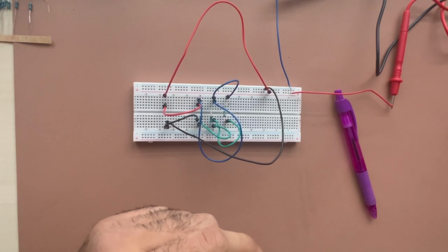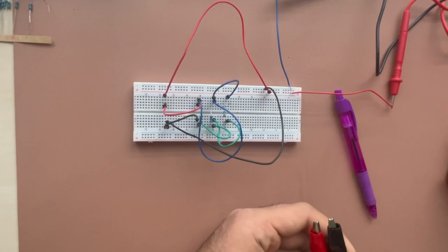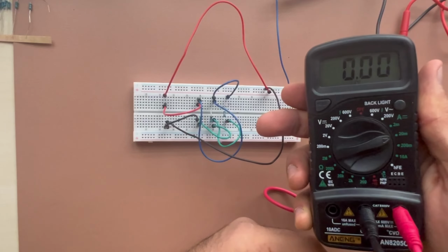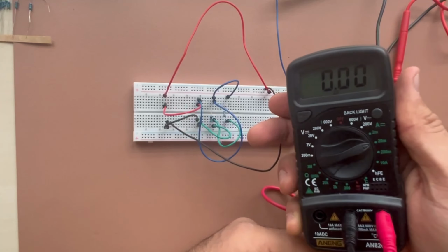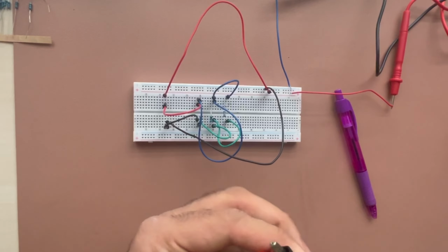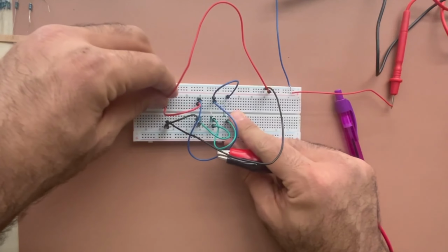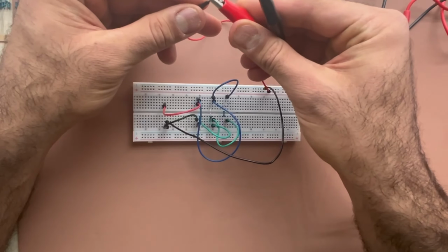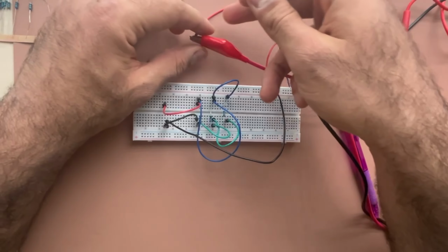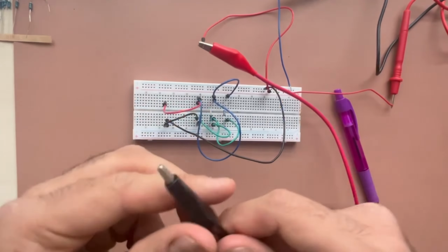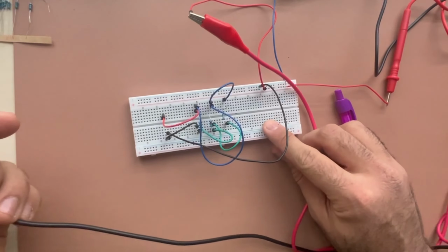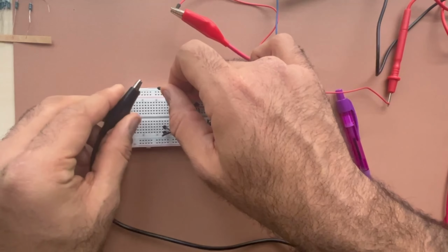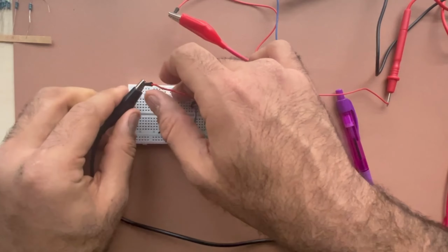Again, turn everything off, and after that, you need to make sure that you have the current section, or the milliamp section, for your ammeter, then connect it to the circuit. So the only thing I have to do is get rid of this wire and connect it to the positive side, because I know current would go through there. This is going to directly connect it to the source, and then I can connect this to the place that my red wire is supposed to be connected to. So I have something like this.